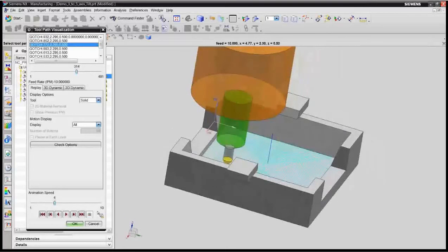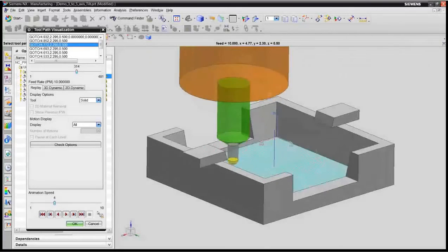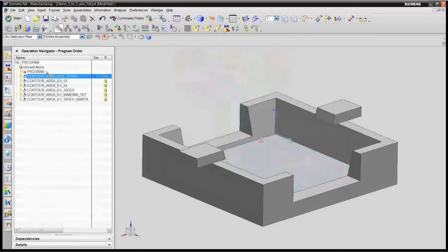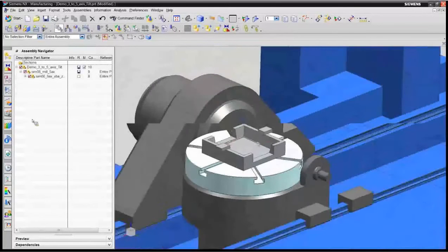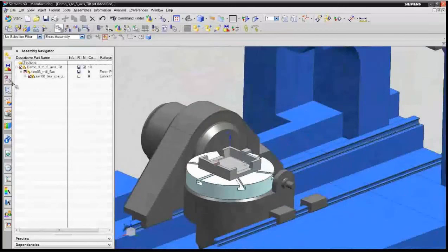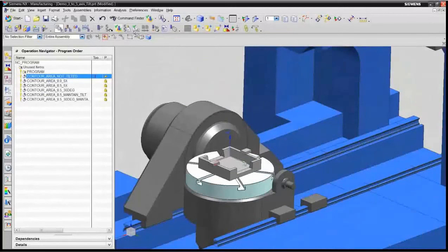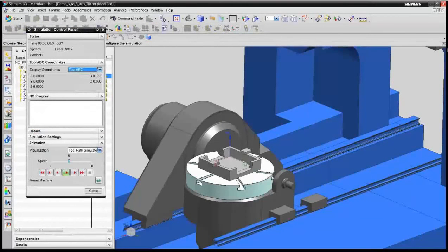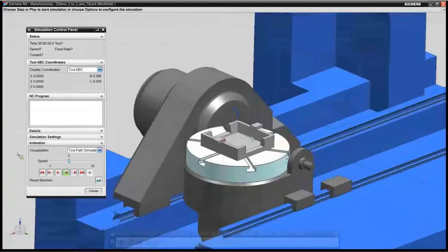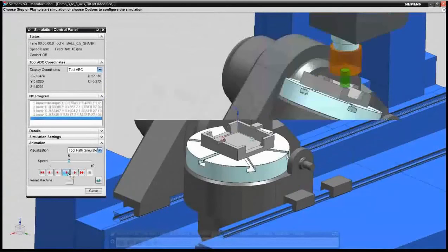So we're back to a 3-axis toolpath that does not have to be tilted, because you don't have any clearance issues there. And so we've actually now gone from the 5-axis back to simply cutting a 3-axis toolpath, which means less motion with the machine. And to take this a step further, if you've got your full machine kinematics in here and you want to simulate that full machine kinematics, that's set up, this 3 to 5-axis toolpath can be simulated. So what I'm actually going to do is go full screen so I get a little more graphics area here. And let's go ahead and run that.